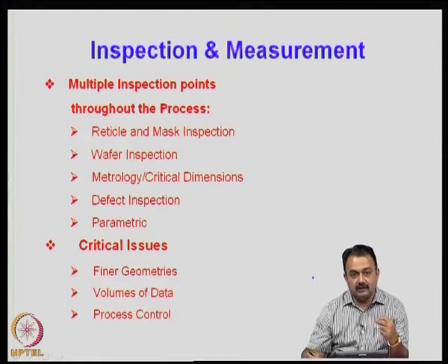I want to emphasize here inspection, measurement and quality control at every stage. The steps that we have mentioned may not exactly be the same, because there may be very many intermediate steps, including rinsing, other methods of cleaning and inspection and so on. So, it takes a while from the silicon wafer to a single die to be complete. At each step the quality control personnel will have to look for various defects and certify it.